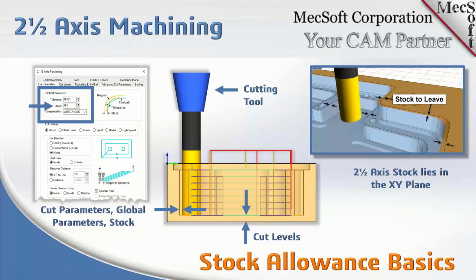Remember that stock is not automatically applied to the bottom of the tool on the bottom of a pocket. You control that with your cut levels. So the slide previous.